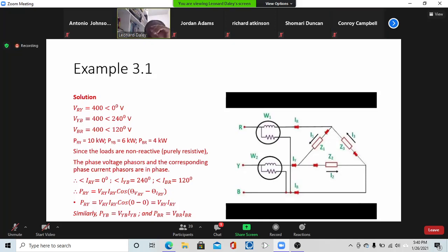All right. Then if we look at watt meter 2, realize now that IY is flowing through watt meter 2's current coil. Everybody clear? Yes, sir. And the voltage coil for watt meter 2 is connected between Y and B. So we know that Y is at the positive potential, B is at the negative potential.